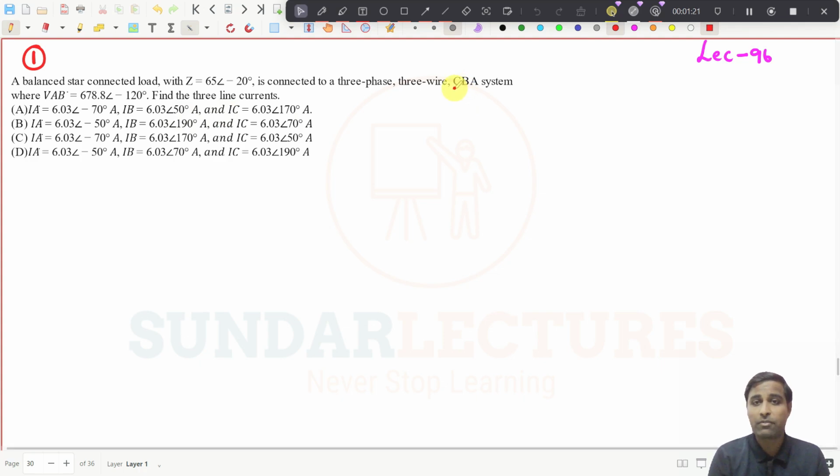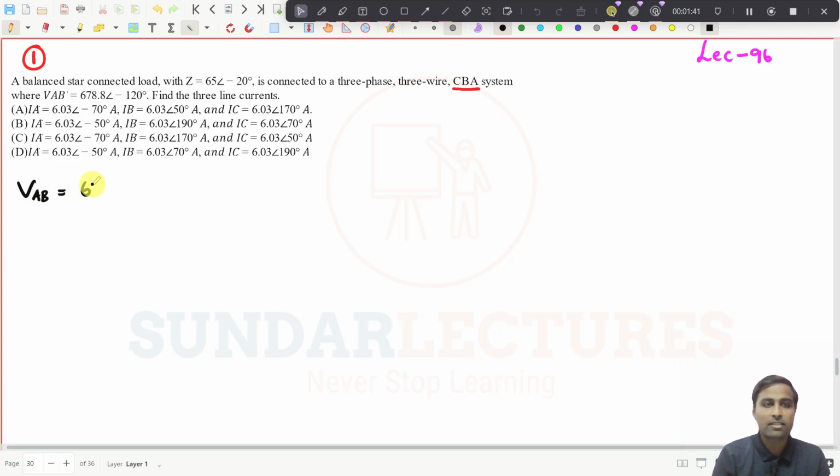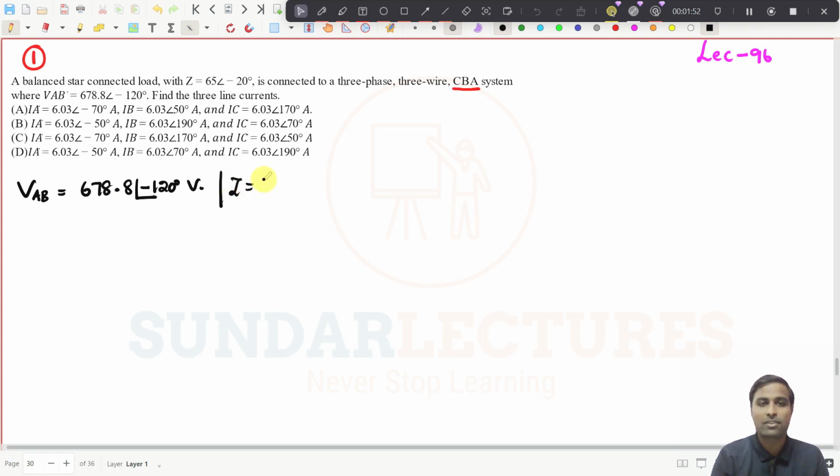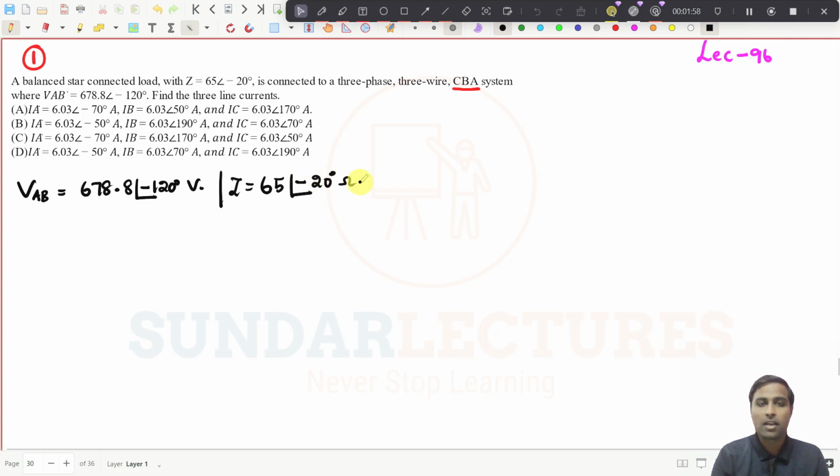You have to be very careful that this system is not an ABC system. It won't follow the ABC sequence. It will follow the CBA sequence. They have given you VAB, that is 678.8 at an angle of minus 120 degree volt. They have also given you the Z value, that is a balanced load, so all the Z values will be the same. These are the two given data.